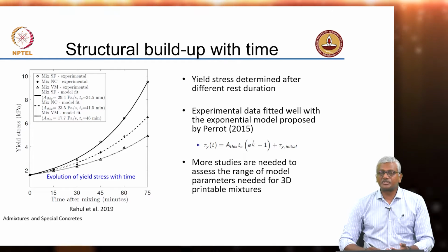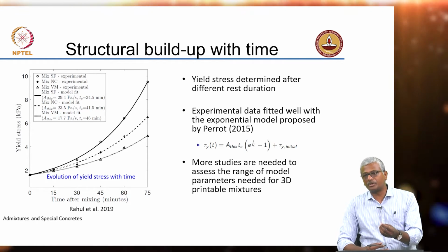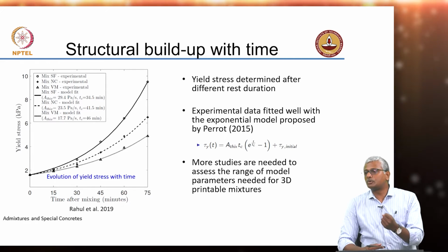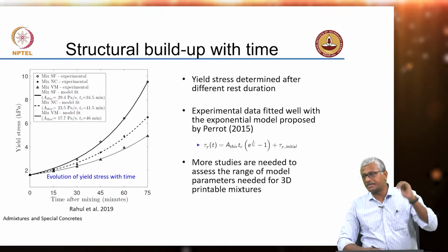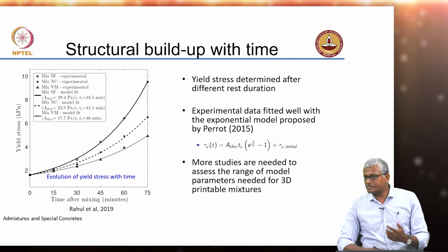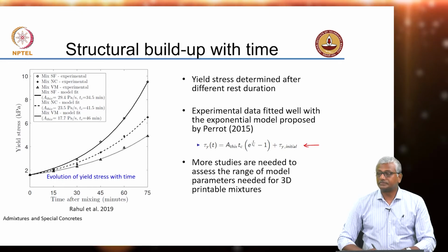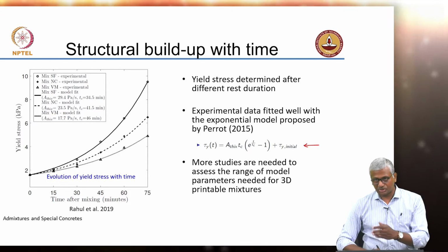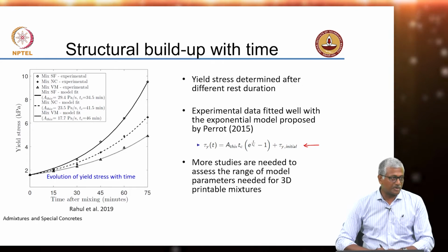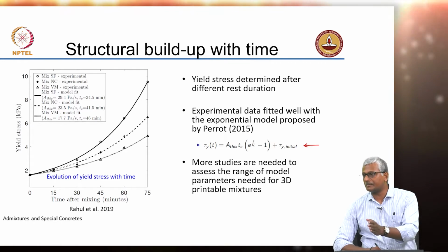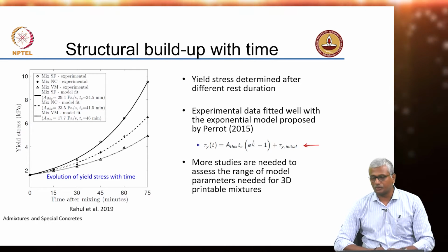And for all these mixtures, the structural buildup, internal buildup, we discussed earlier how this internal buildup is important, because the internal yield stress has to build up to a level that is able to overcome the stress due to the weight of the additional layers that come on top, right. So, we have to understand this behavior also, and as I was telling you earlier, there are non-linear rheological models which can help you fit this equation also. So, you can see that the data which have been experimentally obtained by measuring the yield stress at different times seems to match quite well with the model predictions that can be used from literature.